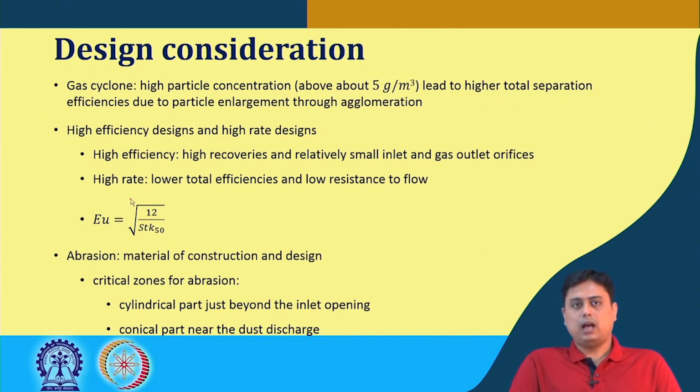Quite naturally, the high efficiency designs provide high recovery of the solid particles or the coarser particles, and have relatively small inlet and gas outlet orifices. That means the resistance to flow is higher. On the contrary, high rate designs can handle a large volume of flow rate because there is low resistance to flow, but it results in lower total efficiency. So based on your requirement, this has to be chosen wisely.